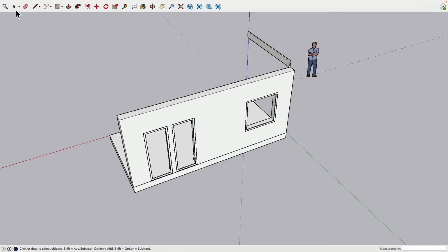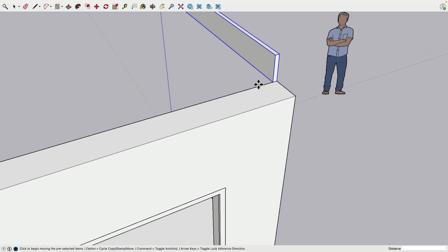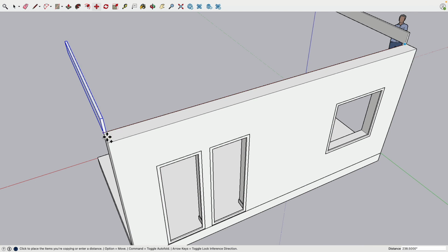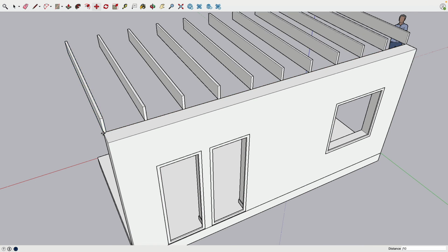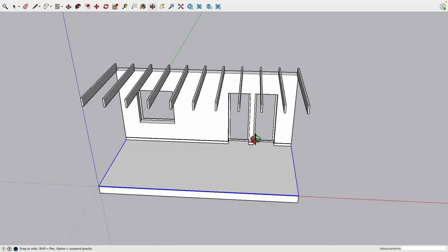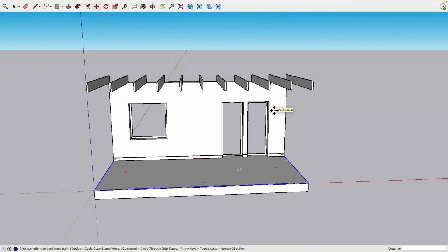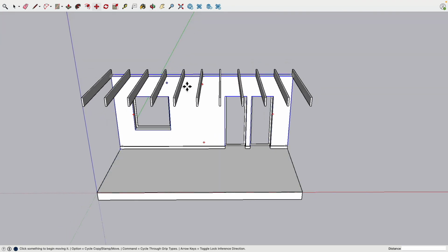Okay, something isn't working. One more time. So you make a copy move from there to here and then divide by 10. There. So we have then evenly spaced out, or filled this space with, 10 copies.